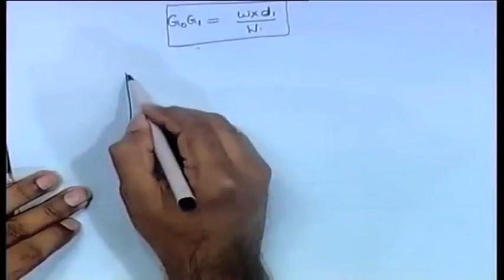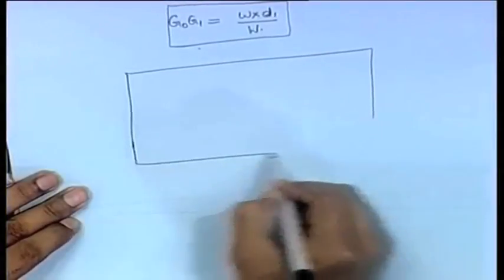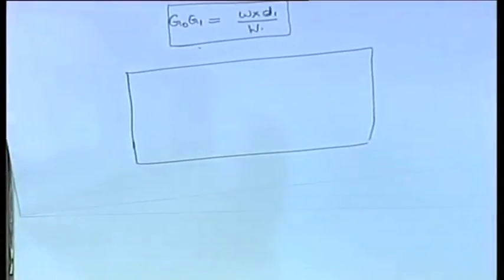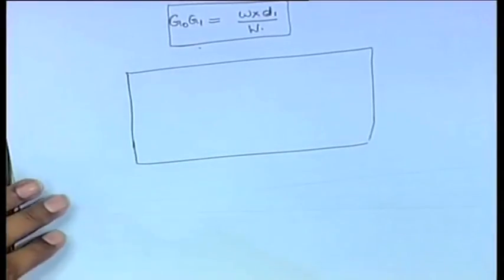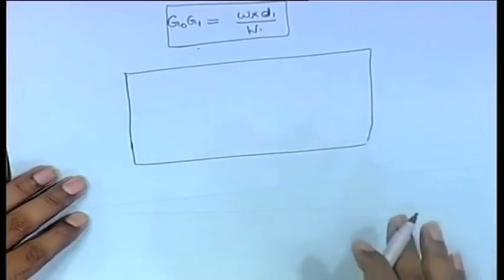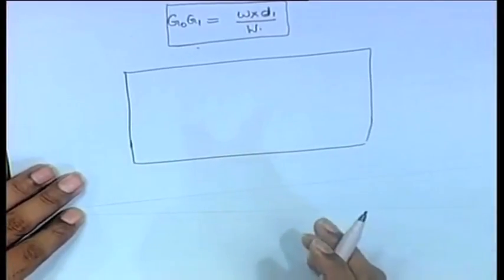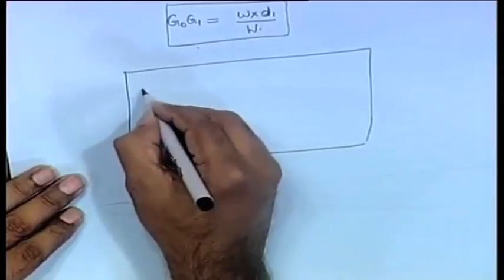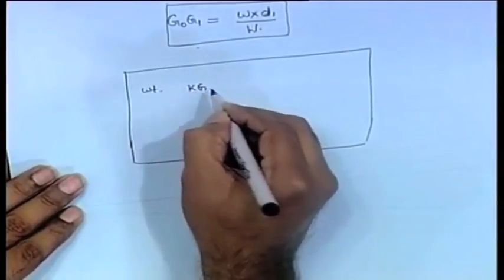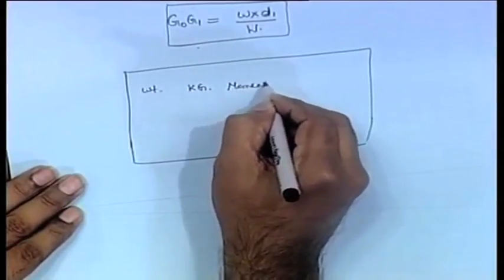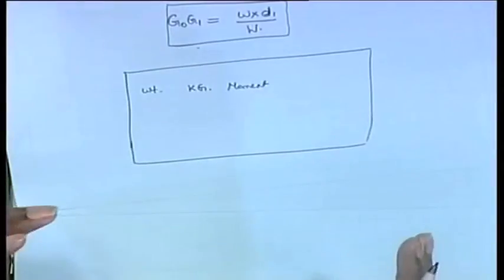Okay. But this way of doing it you should know, that is, this table, one table you should always draw. Please do not write continuously like kg of 1, kg 2, please draw the table and do it, because otherwise mistakes are very common. So, always like this, weight will be there, kg will be next, moment will be next. This much is needed to get your new kg. In any case, some weight will be added somewhere, some weight will be removed somewhere, and the concept is going to be the same thing.